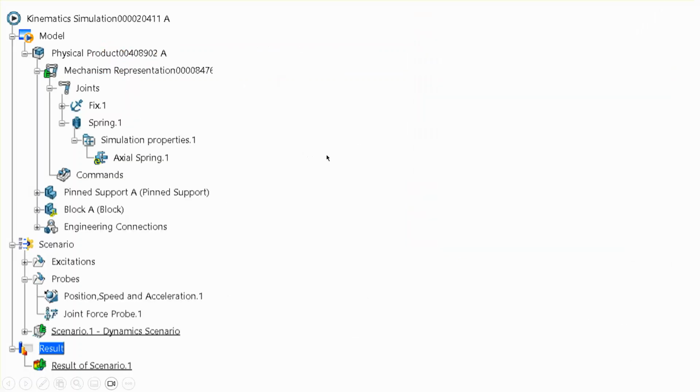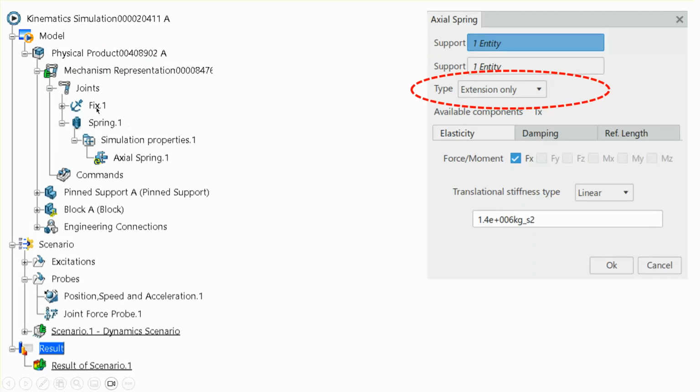What we're going to do is model this problem as a fixed part, of course. That's the support that the thing is hanging from. There's a spring, and that's pretty much it. I've also done this problem insisting that the block moves as a prismatic joint, which is okay, but you're not going to gain anything, at least in this simple problem, by creating a prismatic joint which dictates the motion of that block. So I'm going to use the spring.